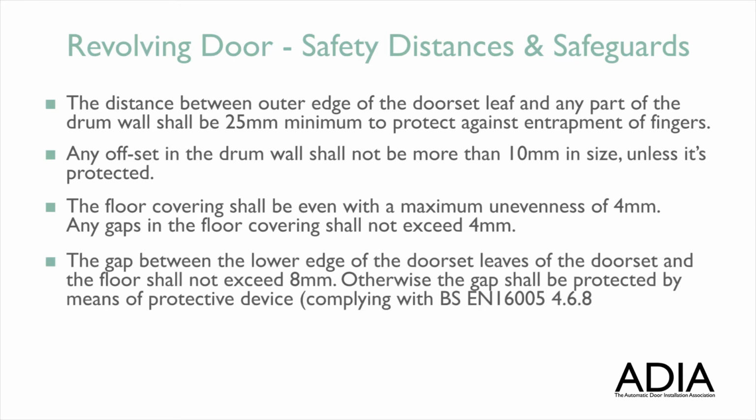The gap between the lower edge of the door set leaves of the door set and the floor shall not exceed 8 mm. Otherwise, the gap shall be protected by means of a protective device, complying with BS EN 16005 4.6.8.